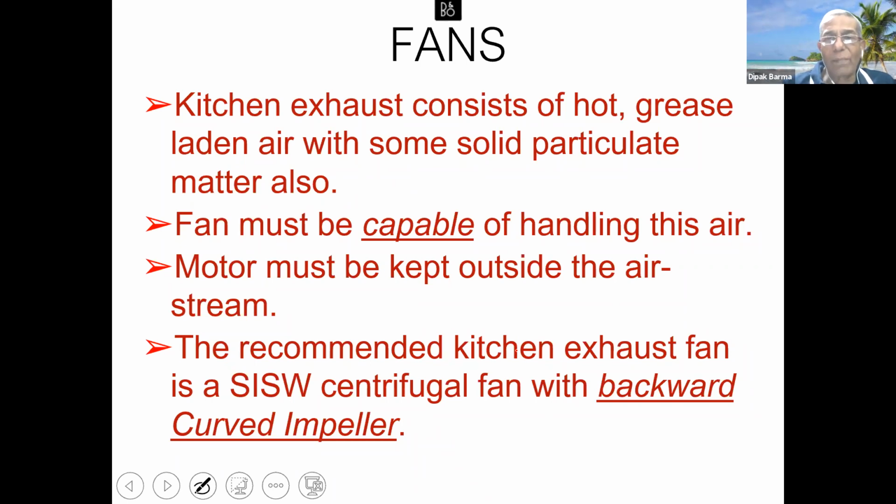But where the exhaust happens, if you use fans with, let's say, forward curved blades, which get clogged, and the deposition of solid particulate takes place on them, it's very, very tough to keep cleaning these blowers. So the best is to use a self-cleaning type blower, which would ideally be an SISW, that is single inlet, single width centrifugal fan with backward curved impellers and not forward curved impellers. This is an important aspect which has to be taken into account.